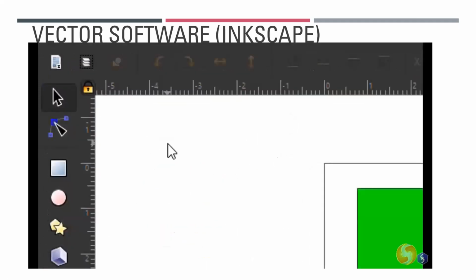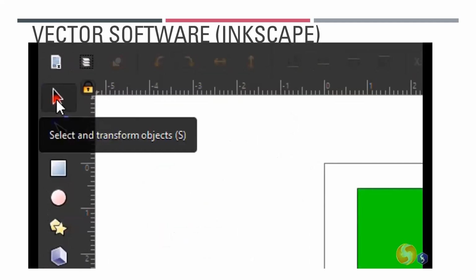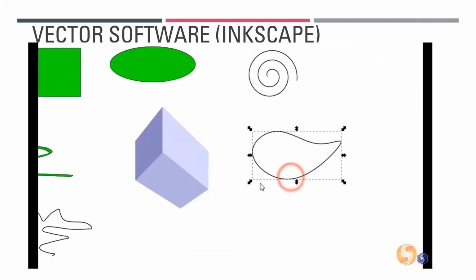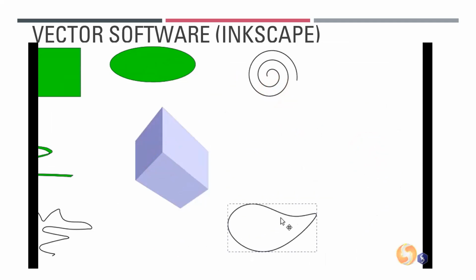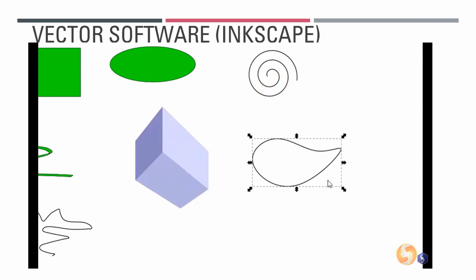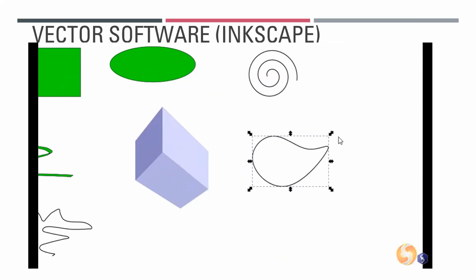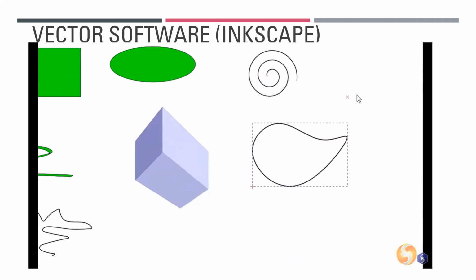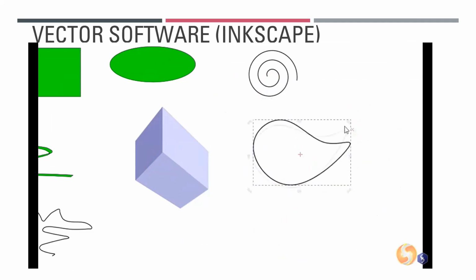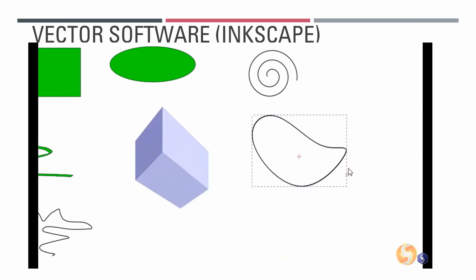Now, let's see how to edit objects with the Select tool enabled. Click on any object to select it, and click and drag it to move it. This shows its dashed box and several nodes you can use to scale the object. Hold down the Control or Command key to save its aspect ratio. Click once again on the object to rotate and skew it instead.